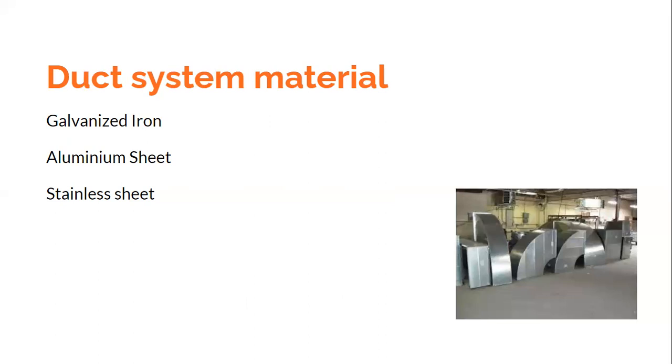Okay. However, the lower aspect ratio allows less material due to lesser perimeter, lesser material due to a higher gauge of sheet, lesser material due to less stiffness required to prevent sagging of the sheet. If there is a lower aspect ratio, then there is a lesser cost of installation, lesser insulation cost, and lesser running cost due to lesser pressure drop. So ideally, we should have round ducts.